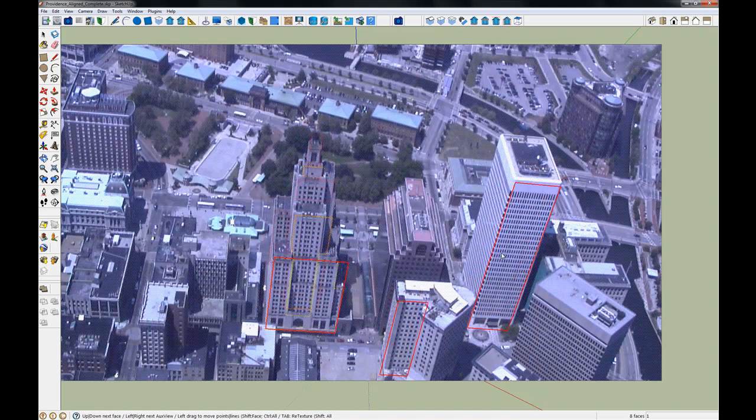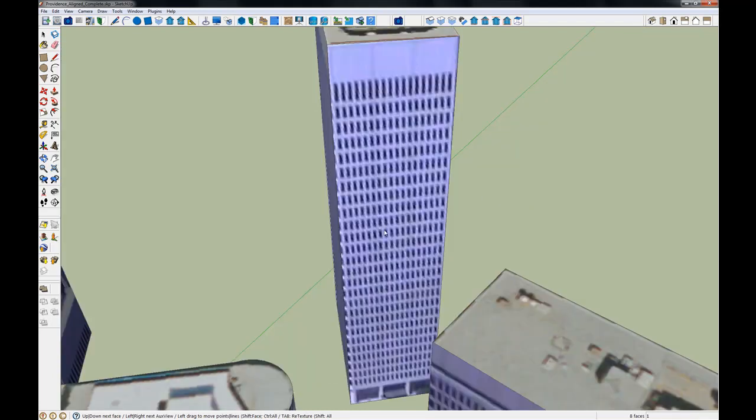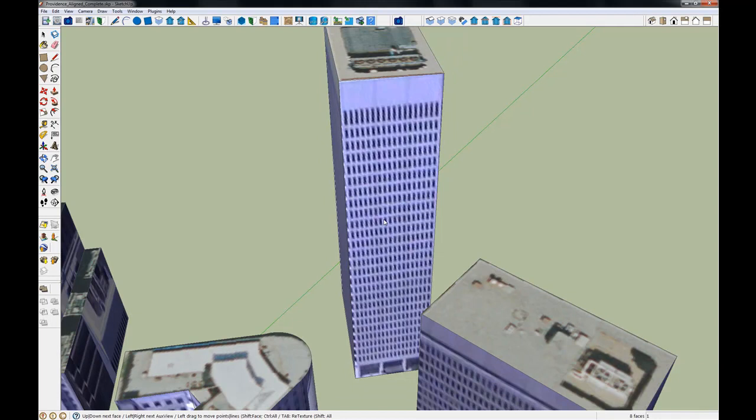It would be useful if, for example, your camera model was off by a little bit. You could make the coarse adjustment for that error, and then of course you can go into the individual faces and move those. For example, take this bottom edge and move it over a little bit to change the skewing of that texture, and then when you hit the tab key, it'll focus in on the model of that area to show you what the texture looks like.